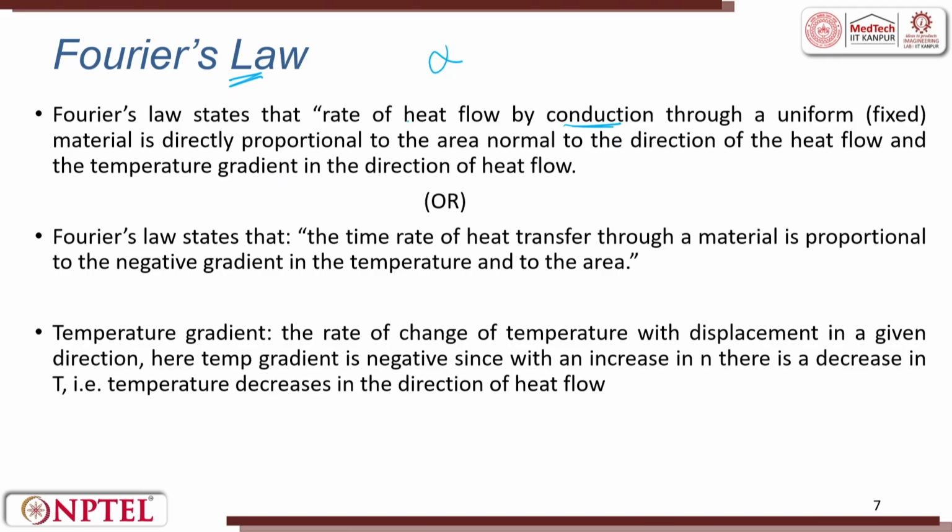Two important points: the rate of heat flow by conduction is directly proportional to the area normal, suppose it flows like this, this is an area, normal to the direction of heat flow, and to the temperature gradient in the direction of heat flow.